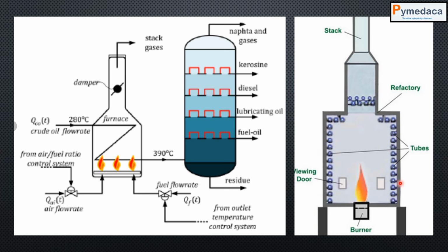So this is far more important actually. And also when you review the vendor package, you will have to see whether the vendors are complying with all the piping requirements, whether proper supports are provided, and the right materials and right pipe thicknesses are used and everything. Those things can be ensured basically.